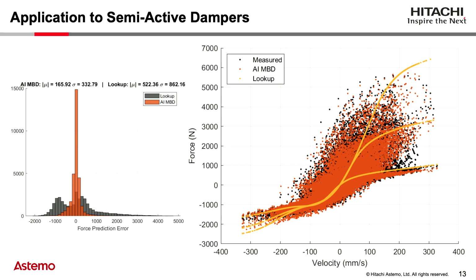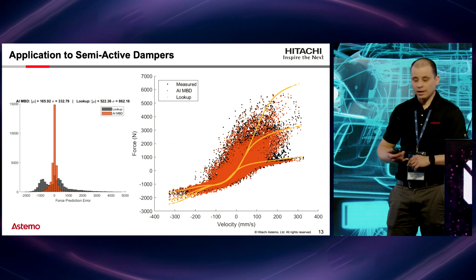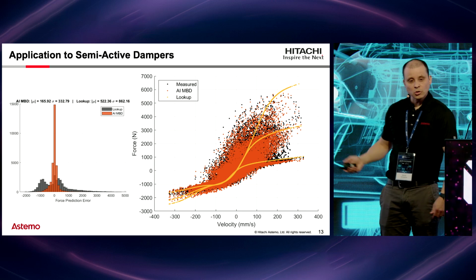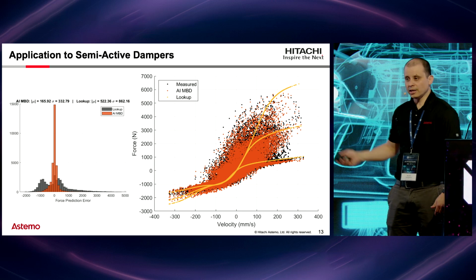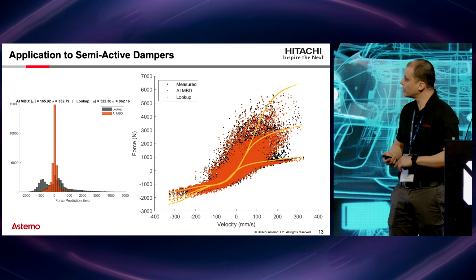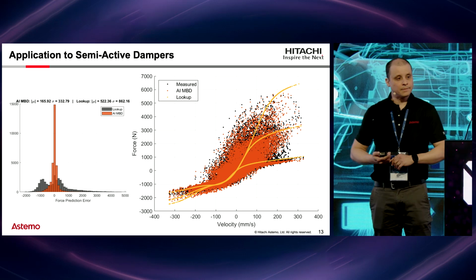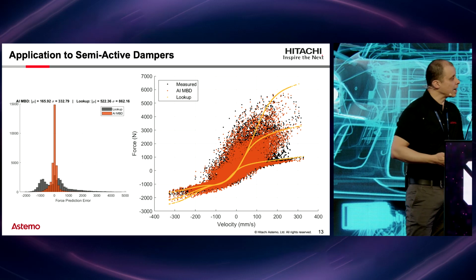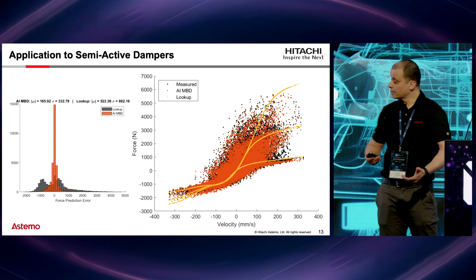Another application is for semi-active as well. Sometimes we go for runs, full vehicle simulations. We do some co-simulations with the logic together, but we mostly base our tables on 3 or 4 fixed currents. And sometimes we are not able to get the interpolation between them, or we need to do some calculations for that. So this is a good application for this kind of damper models as well.